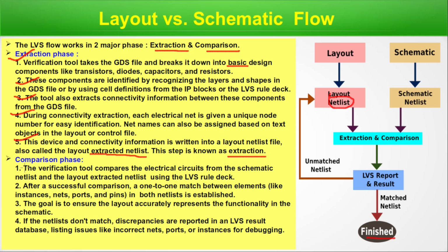Now, what is the comparison phase? The verification tool compares the electrical circuits from the schematic netlist and the layout extracted netlist using the LVS rule deck. After a successful comparison, a one-to-one match between elements like instances, nets, ports and pins in both netlists is established. The goal is to ensure the layout accurately represents the functionality in the schematic.